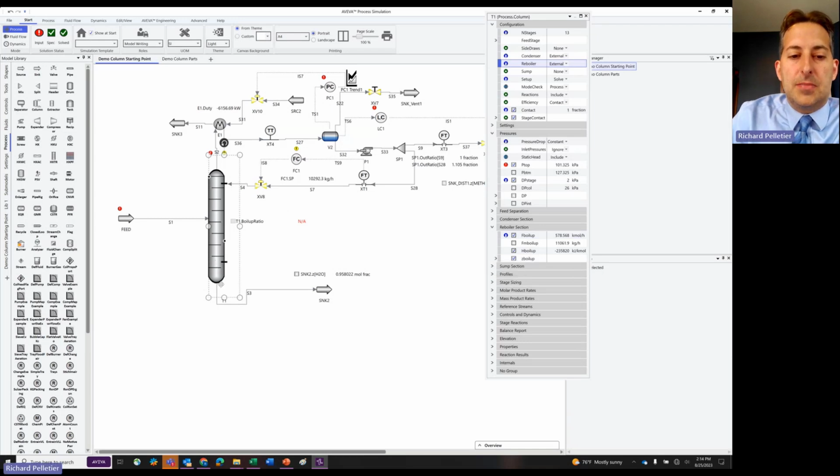We are going to have a sump here because we're going to try to draw off of the sump to go to the reboiler. The product of the column, the bottom's product, is still going to be this stream coming off, but the reboiler itself is going to come off of a separate draw and then return back separately as its own loop within the column. Right? So when we do this, we need to add a sump.